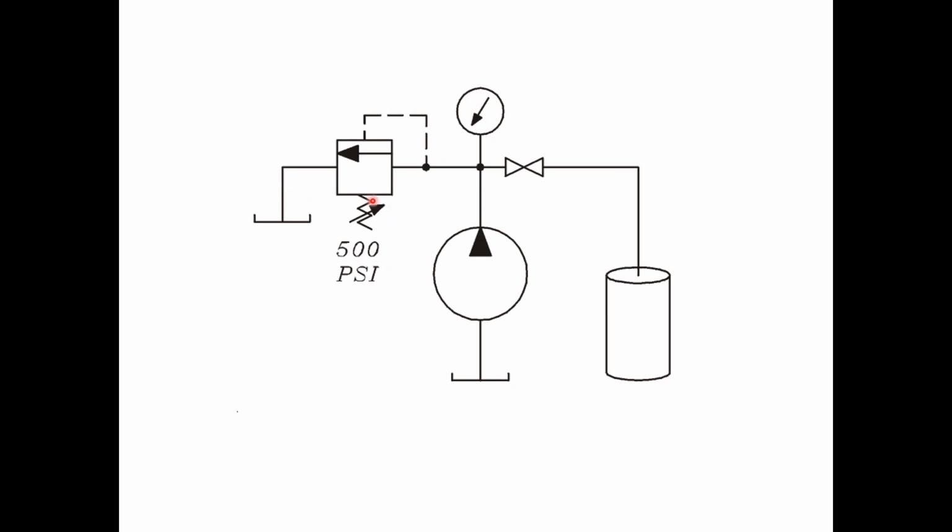So looking back at the spring again, you'll see a 45-degree angle arrow. Right, and that arrow on any hydraulic component indicates that it is variable or adjustable. So whenever you see that on a hydraulic component, you know it's adjustable. More often than not, that component is going to have a knob on it, something for the knob turner to get his mitts on. Every plant I've ever been to has at least one of those. The knob turner's name is usually not me.